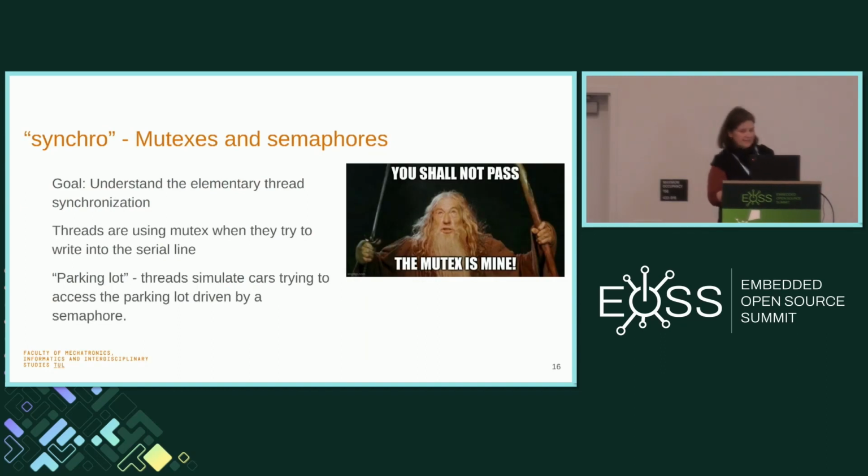And then again, the second most important part, which I am supposed to teach, are the mutexes, semaphores, and synchronization, because again, in the next years, they will need it quite often, and they need to understand the process. So for this, we have a lab which was really popular in Embed, because we had nice displays full of colors, and the display serves as the parking lot. So you have 4 spots in your parking lot, and you spawn 10 threads, and those threads are cars.